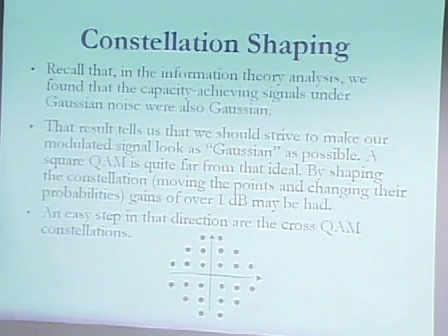In DSL, they use huge constellations, very large. I don't know if any of you uses DSL at home for high-speed internet access, but they use constellations with thousands of points. So the shaping becomes pretty important when you have thousands of points. Here you only have 32. In wireless, no commercial system has more than 64 points. But in DSL, they sometimes use thousands.